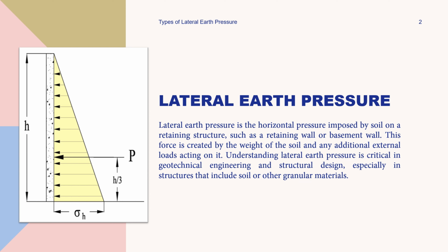So, we can see in the figure a wall with a height of H subjected to a load P. Because of load P, pressure is imposed on the wall. This is the concept of forces from mechanics: a load acting on a section produces stress or pressure on that section. The pressure produced by load P is the lateral earth pressure, denoted by sigma H. Understanding lateral earth pressure is critical in geotechnical engineering and structural design, especially in structures that include soil or other granular materials.